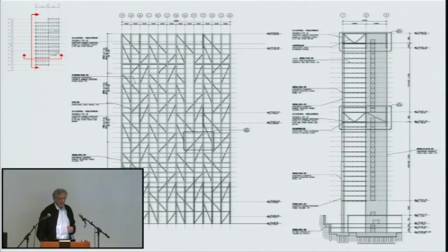And certainly at this scale, it does come down to these kinds of drawings where you have core systems and you have this screen system that gets load from outriggers that interconnect with it when the building moves laterally. But as those loads get into that frame, they distribute down and equalize and activate all the vertical elements before these forces get to the ground.